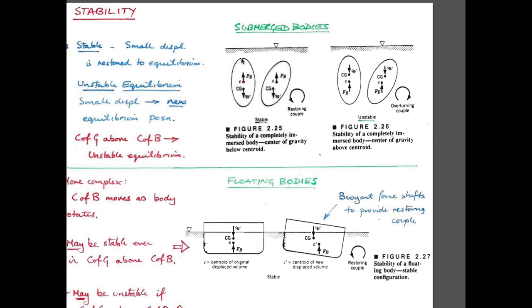So it's always going to be on an axis which comes down through here, and also the other axis as well. The center of gravity, for instance, in this particular case, would be a situation where there's a denser material in the bottom, because the center of gravity here would also be the same place if this was a uniform density material that was inside, submerged in the water, say cork, which is lighter than water, mainly air. But if it's denser, but if it's something where, for instance, most of the load is in the bottom half, then the center of gravity is below the center of buoyancy.